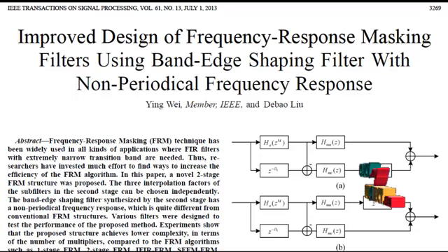So, the drawback of FIR filter is overcome by the frequency response masking technique. In this technique, first of all, the filter is interpolated to get the transition band. Then the interpolated filter and the complement are masked. Finally, the result is obtained by combining all these together. This leads to low arithmetic complexity.